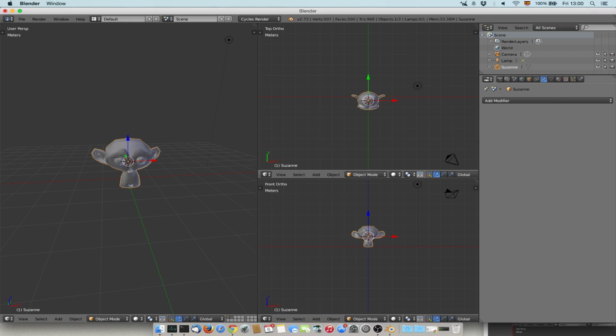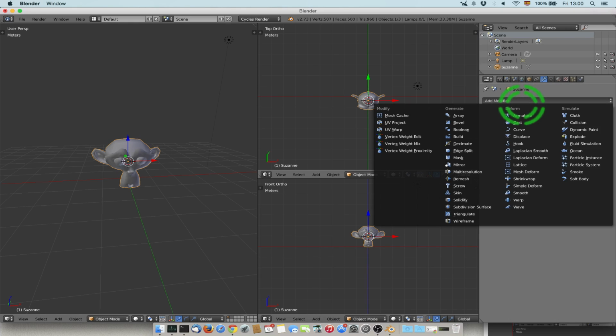This is basically a way of doing some modification on the mesh. So for example, you click on this and you add one, and they stack on top of each other. So you can add more than once. And until you click apply, they are dynamic. That means that you can change the values. If you click apply, they generate the geometry, and then you cannot go back.